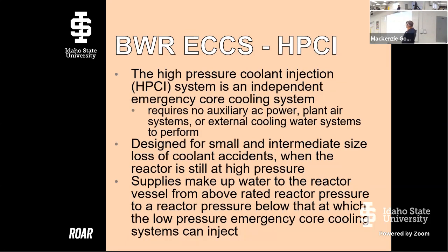The high pressure coolant injection system is the main ECCS. It requires no power or external cooling water, and it's designed just like in a PWR for small and intermediate sized LOCAs, okay? It provides makeup water when the reactor is still at rated pressure, okay?